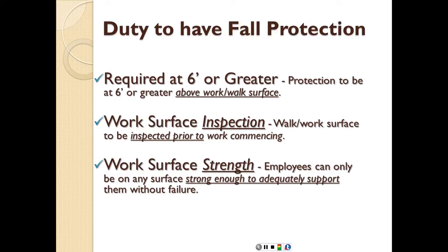Work surface strength, again, if you're going to be working on the cover of a hole, for example, if that's going to be your working surface, then you have to make sure that it's not going to break under the weight of the employee and any tools or equipment used by that employee. So employees can only be on any surface strong enough to adequately support them without failure.